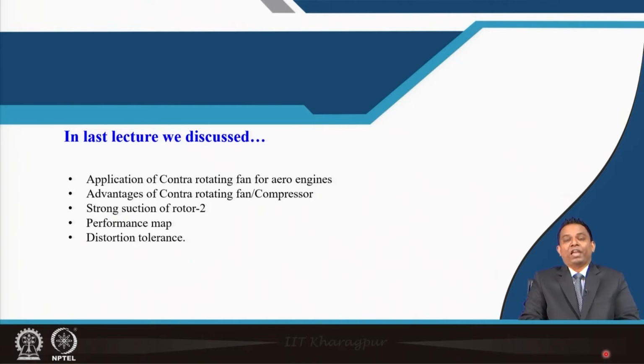Okay. We have seen our own experimental results showing the performance of the contra-rotating fan, and they say we have a wider operating range compared to our conventional stage. Wider operating range means the two extremes, maximum mass flow condition and minimum mass flow condition. We also observed that the contra-rotating concept gives two kinds of stall, called partial stall and full stall configuration.